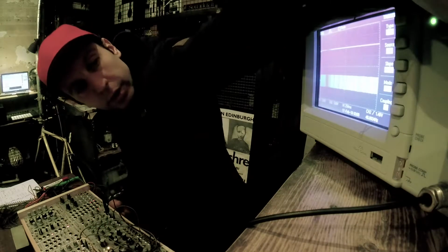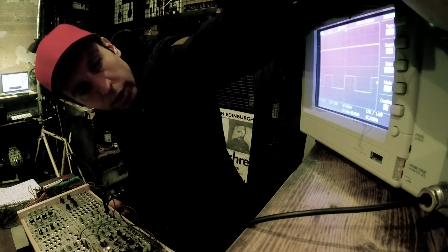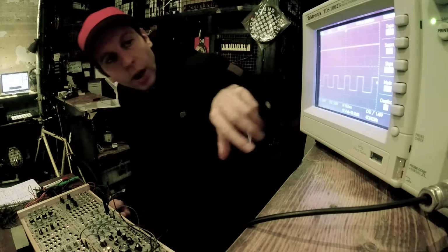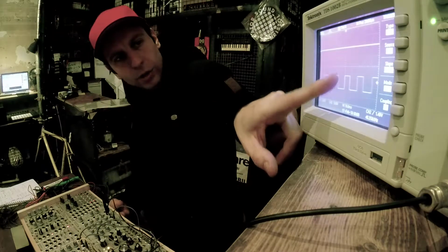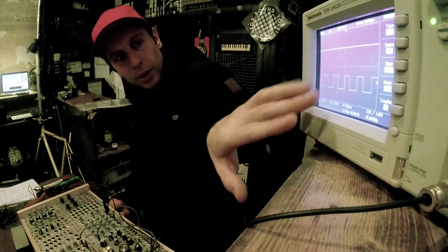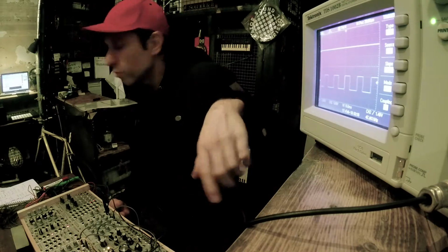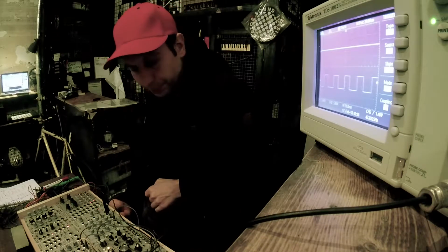You can hear it, but the tricky thing right now is that, oh yeah, there you go. So you see now I'm triggering on the edge. This edge of my square wave here is fixed to the y-axis, so you see the rest kind of moving left and right. So that's the change in frequency, so to speak.